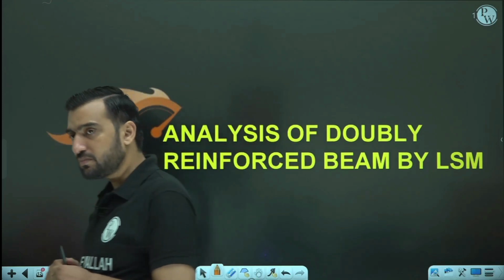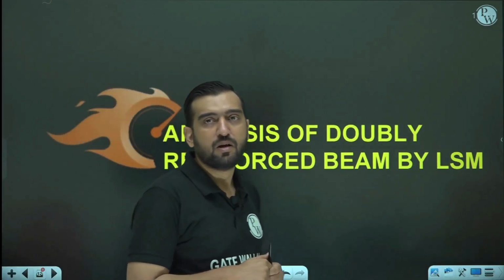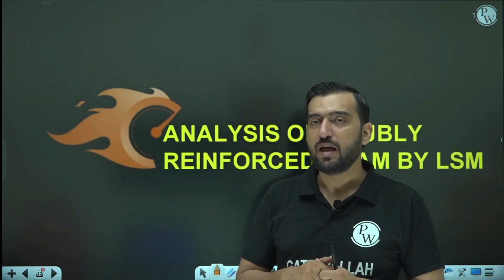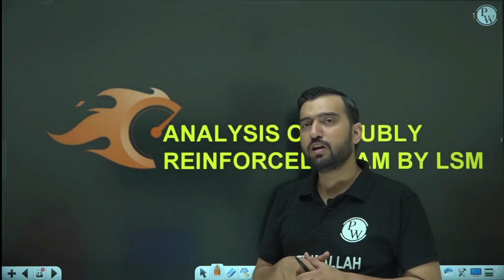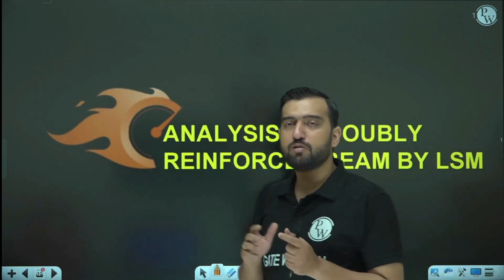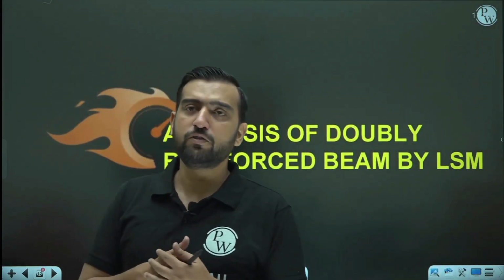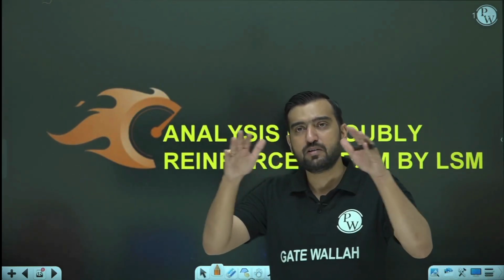My dear friend, whenever we want to resist more amount of bending moment than a singly reinforced section, as we know that the limit state method is not supporting over reinforced section. So had it been a case of WSM, in that case we could have easily increased the amount of steel and gone for an over reinforced section, and we would be able to resist more bending moment with a limited size.